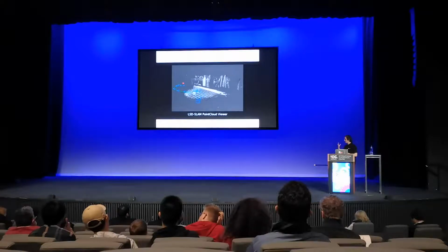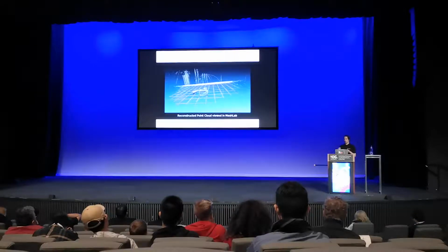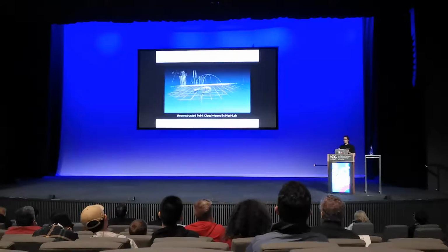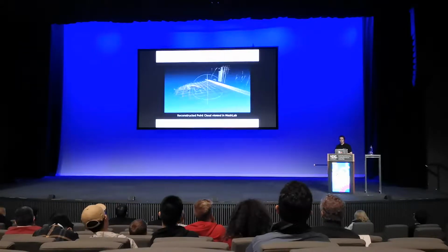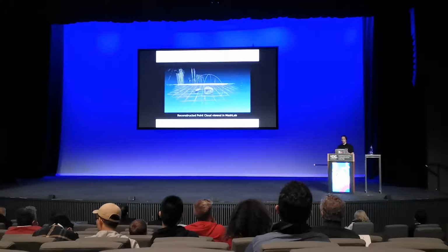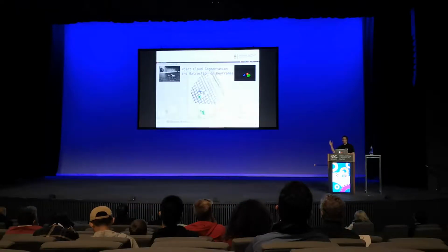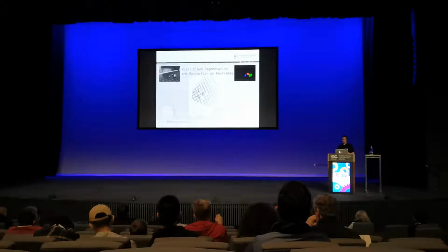The interesting part is that we have to finish the point cloud, but we also have to extract the individual part point clouds out of these. So our approach is doing a semantic labeling on the RGB image with the CNN network. This allows us to just select the points out of the point cloud that belong to the objects we are interested in. You can see the keyframe on the left, on the right you have the labeled image, and I color-coded the objects there. This allows us to extract these single point clouds out of the image based on what object we are interested in. There's another labeled keyframe here, and some other point clouds.